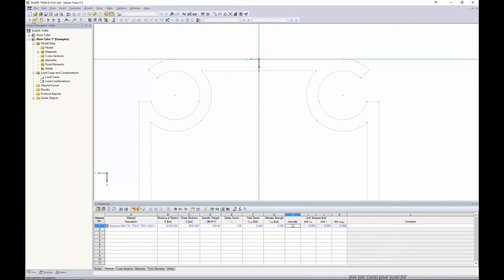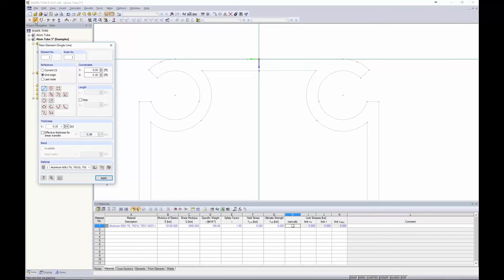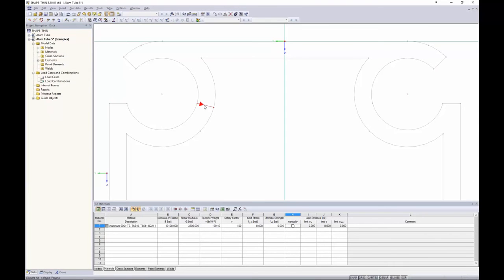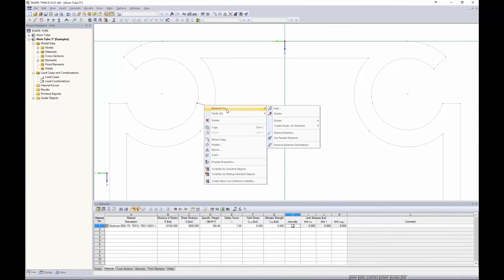Now, the first option we want to go to is this new line up here in our tools. We have a straight line selected here, but I'm going to select a thickness of 0 inches. So all I'm going to do is to snap to one of these points on my arc and snap to the other point that's perpendicular to it. Now, there are a lot of AutoCAD-like features such as snap points, perpendicular, parallel, that allow us to utilize these features quite nicely.